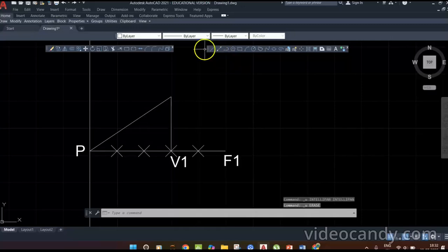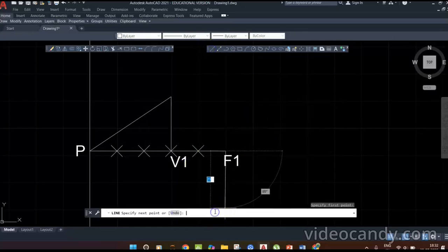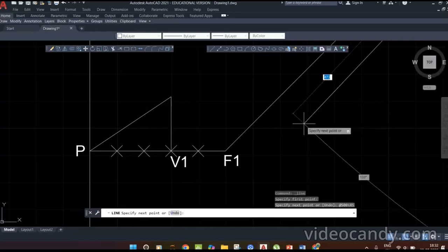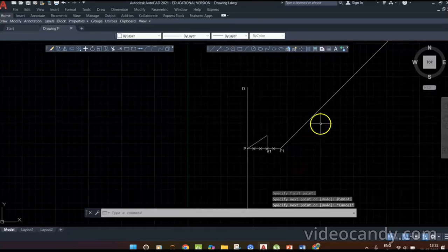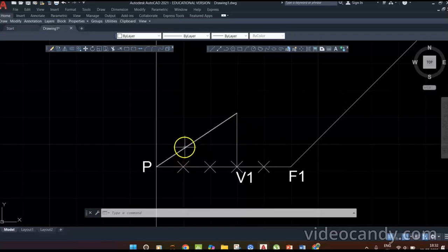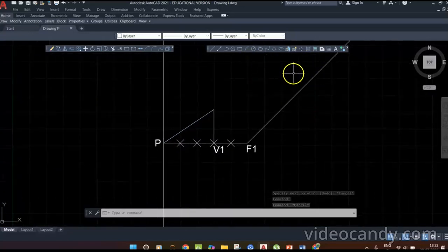Okay. With focus as center, draw a line. To find the second vertex, we adopt this method. From the focus, draw a line at 45 degrees with respect to the horizontal by using the command @ with some arbitrary length, at less than 45 degrees. Somewhere it enters into the infinite space, right? So the main agenda is we should project this line onto this 45 degrees line. Okay, how are we able to do that? Use this method. It will be very easy.